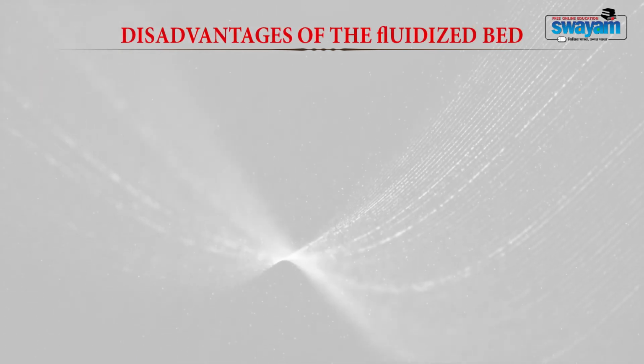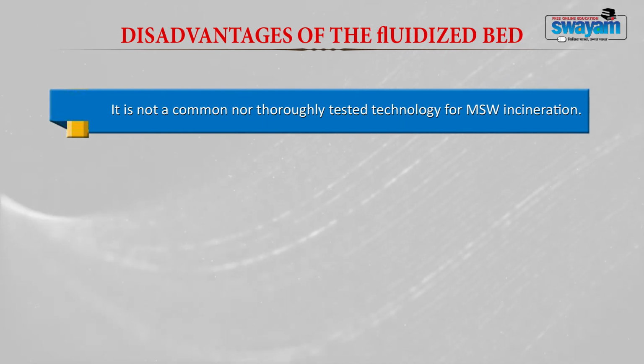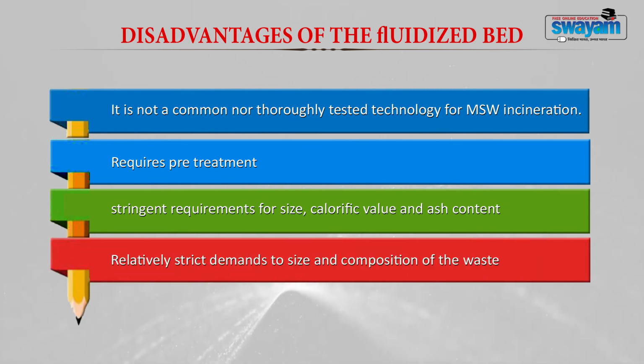If you talk about the disadvantage, this type of incineration process is not very common and is not popularly used. They require pre-treatment, they have stringent requirements for size, calorific value and ash content. They are relatively strict and they demand a particular size and composition of the waste.